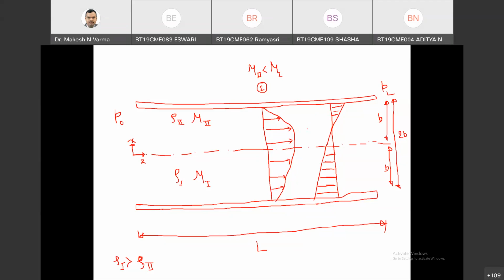Which is the important property deciding negative and positive flux? Velocity or gradient of velocity? The gradient of velocity, dv by dx. So here the flux is 0. This is the direction of momentum flux, in the positive x direction.